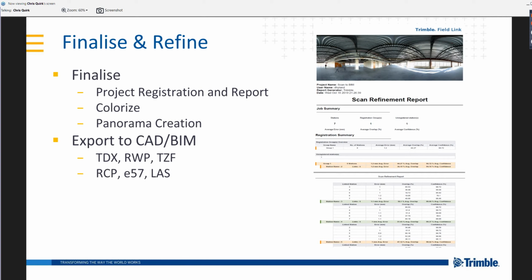And finally, on the tablet, we can finalize and refine the point cloud. So at the moment, there's other solutions that are available on the market that will give you a registered point cloud as you scan. But quite often, this hasn't been refined. It's just linking on to the previous scan station that it's done. So what we do is, before we go to site, you'll have a partly registered point cloud, so you'll be able to see what it looks like. You can analyze it, you can view it, you can check you've captured everything you want. Then when you're happy, you can finalize and refine this.